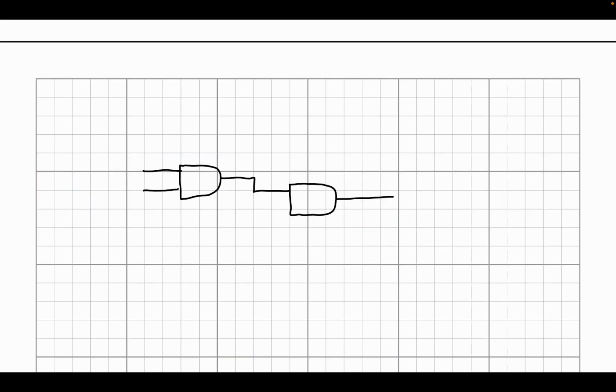So here I've got a simple logic diagram of two AND gates. And usually when we see a drawing like this or a logical expression like this, we don't think of it in terms of the actual voltages that are implemented in the hardware. We think of it in terms of this abstract 1 and 0, and we know that deep down, 0 corresponds to ground and 1 corresponds to like 1.2 volts or something. But in order to understand Fanout, we need to talk about 1s and 0s as actual physical voltages that are actually in a transistor circuit.